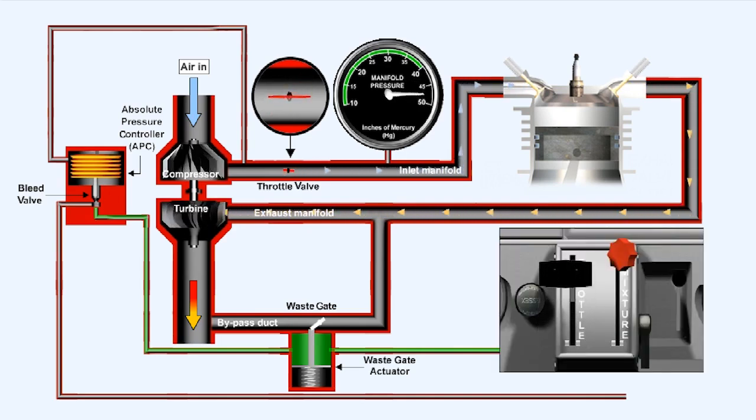The result is that the turbocharged engine's boost, or manifold absolute pressure setting, will require frequent adjustment, particularly if the pilot moves the throttle valve quickly, not waiting for the system to stabilize before making further adjustments to the throttle. The use of a differential pressure controller will help to control these unstable conditions, which are sometimes called bootstrapping.